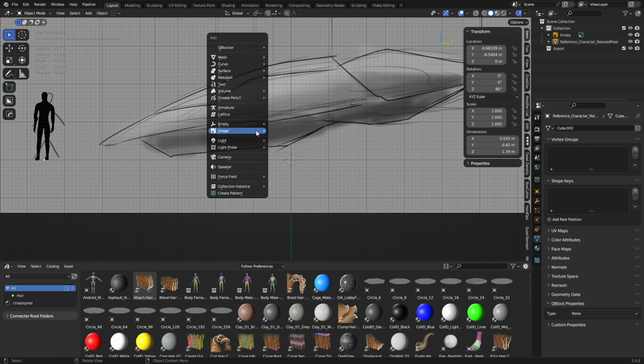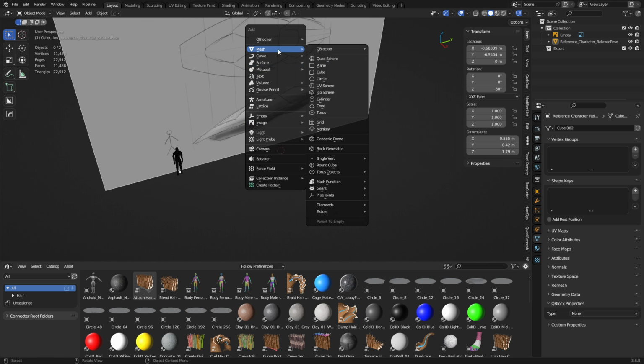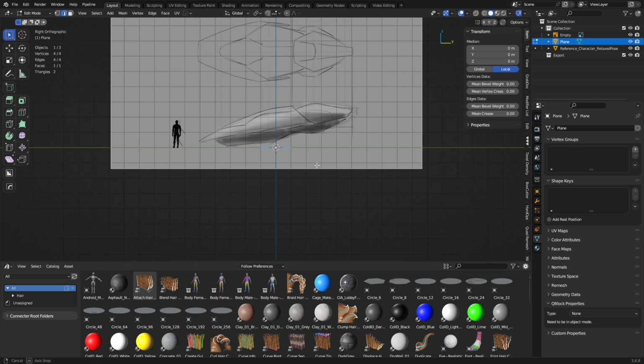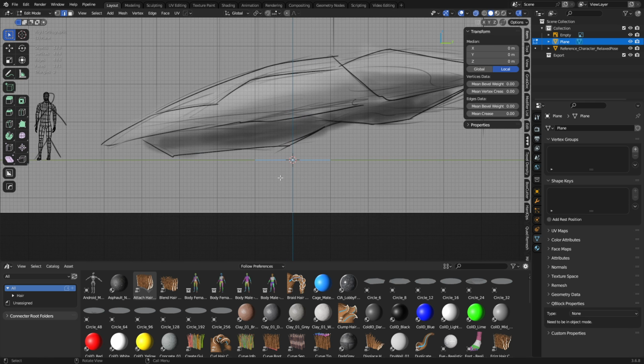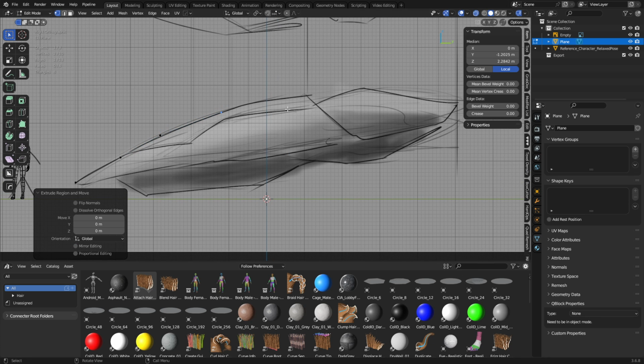All right, and so now you can start modeling on this stuff. Use a plane. So that whole subdivision modeling practice with the plane applies here. You don't have to subdivision model it necessarily. Hit Alt-Z, grab some vertices, and just start pulling them around. And I should be able to hit E and start extruding. We'll do the overall form first, I think.